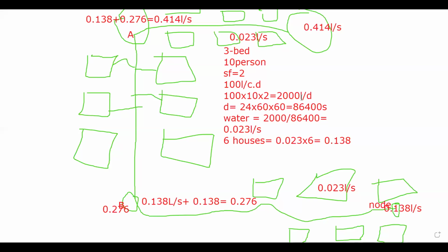So from what we did last week, what is the pipe size? For you to do a pipe size, you need the value for the slope. You need to know the slope of the ground. From the German standard, which we are using, the maximum slope expected is 4%. If the slope is more than 4%, you assume 4%. This is engineering. The maximum slope in every pipe network is in your book.